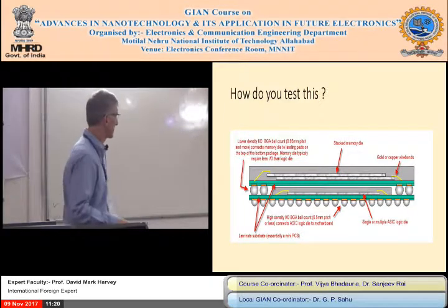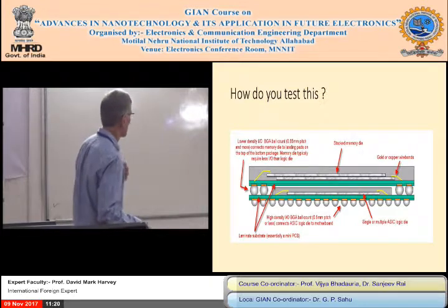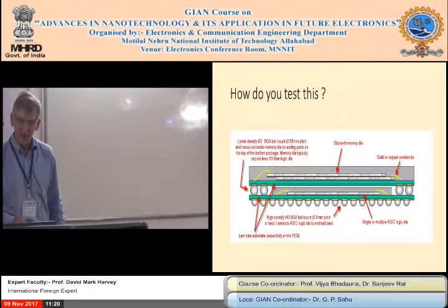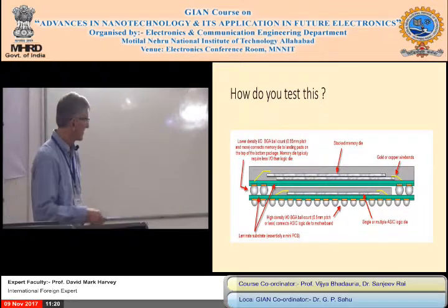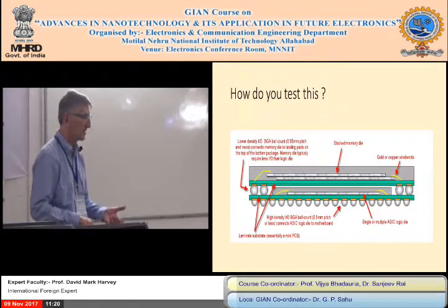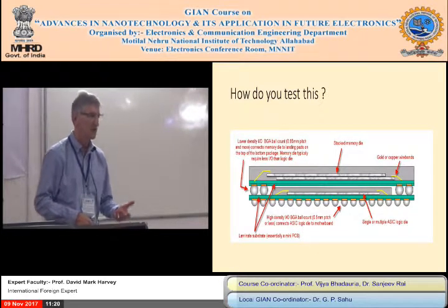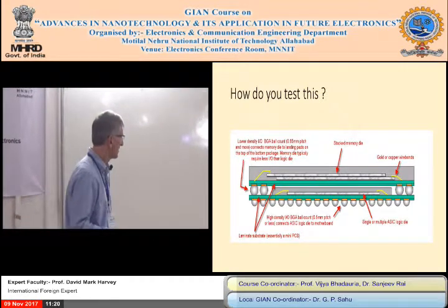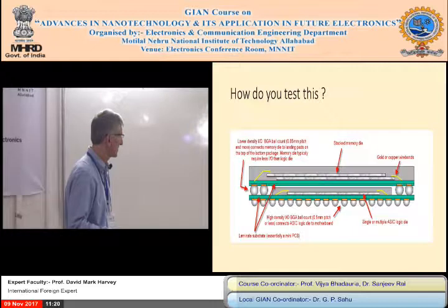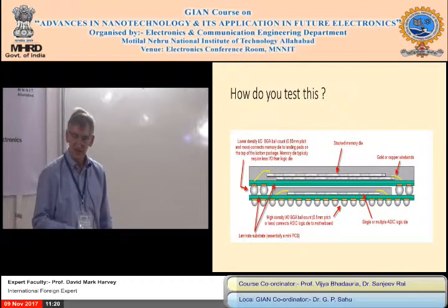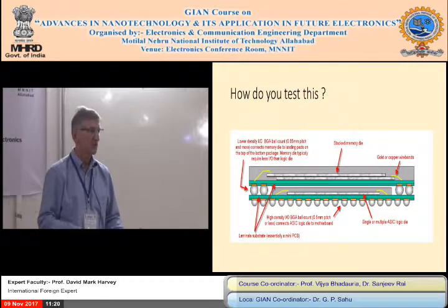Most of the things you want to look at are hidden. Okay? So inside there you've got multiple die. These are what we call stacked die. Could be memory. You've got chips there, and as I said earlier, in the latest Intel chips there'll be multiple die. You could have 4 die on that board, all connected together. Multiple interconnections. You have what you call interposer boards, with solder balls on the bottom and the top. One of those connections breaks.